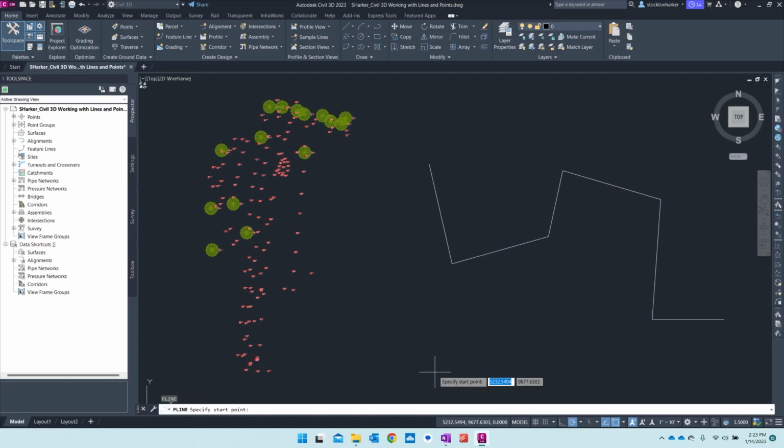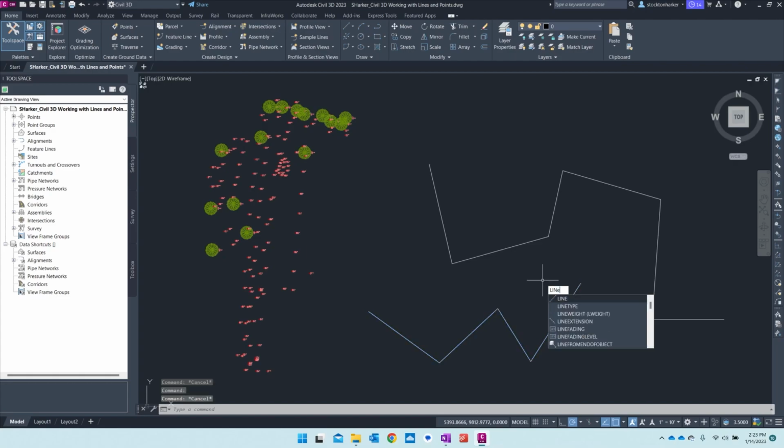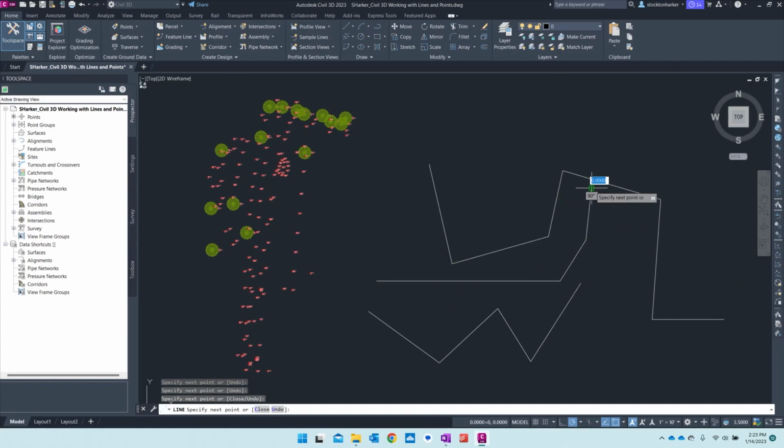To work with a polyline, you put your cursor where you want to start the line, and then you click, and it'll start drawing the line. And then wherever you want to add a vertex, you're going to left click again. It'll keep adding these vertices. This is different from the line command. Line is LINE. That's the line command. And a line command will only draw lines, but each one of them will be individual line segments. So that's the difference here.